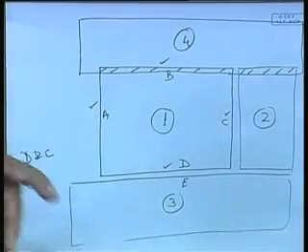How do you cut? Manually, can't help. That is what is referred to as cut at sight. The structure is there, the other structure comes, it is aligned, and you see so much overlap is there. That was purposely kept, extra green material was kept. Why? Because I am not sure how much the panel will shrink this way or that way.